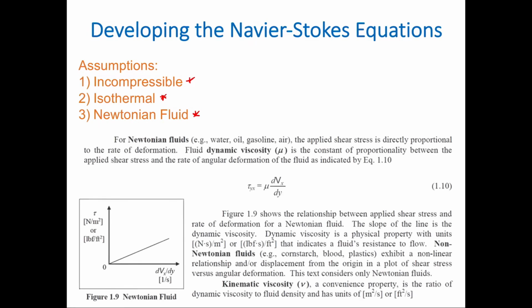What does the last thing mean? Right, so let's do a quick reminder. Newtonian fluid, this is from chapter 1, means that we have this description, which we actually wrote down in this exact class or exact discussion just a little while ago. It basically means that the fluid deforms linearly as a result of a shear stress. That's all it means. It means this is linear.